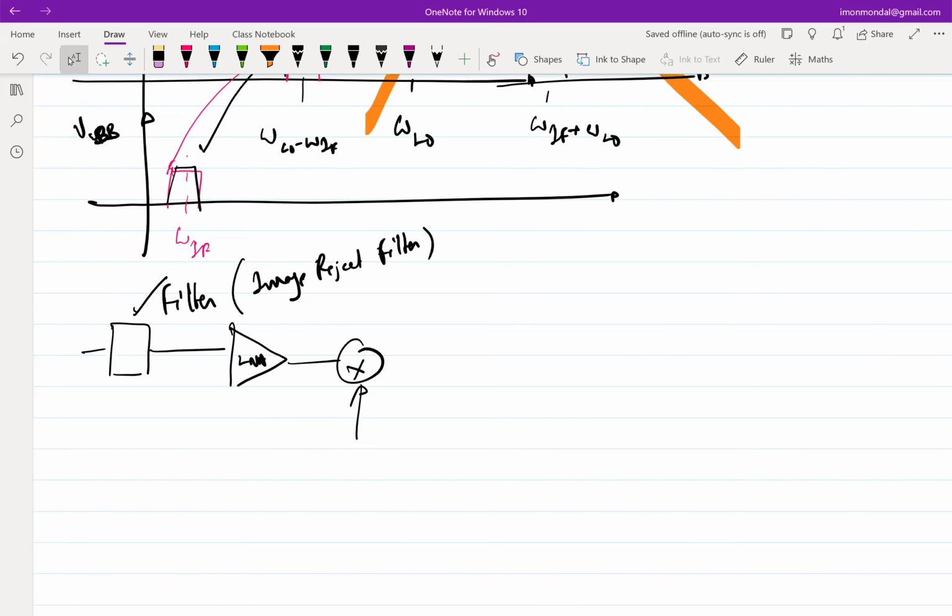What else? Yeah, true. Noise of the filter can add before the LNA. That definitely is the case, because it is right upfront in your signal chain. The purpose of the LNA was to amplify without adding too much noise. If you put something before the LNA, it's going to first add noise, then amplify.